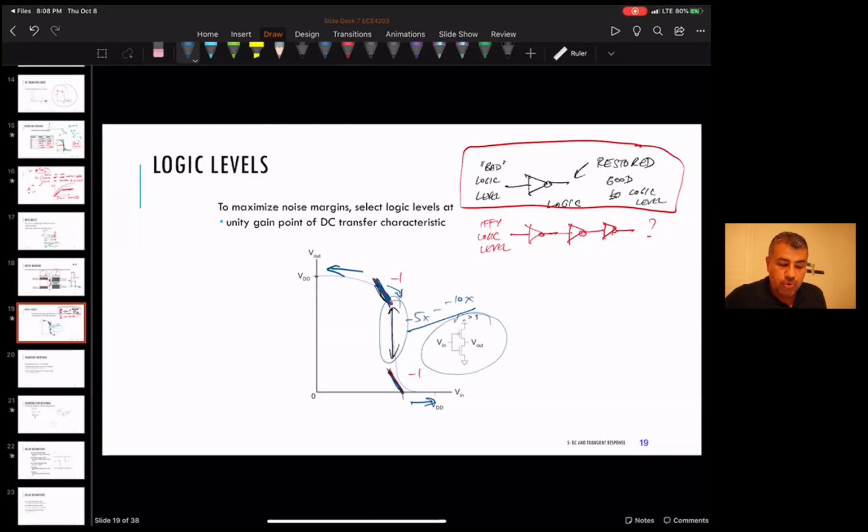Okay, so that's it for the transfer function, and you guys saw this by changing the relative widths. Theoretically speaking, the ratio you're changing is width over length, but length reduces the current of your NMOS or PMOS, while it increases the gate capacitance. So people don't do that in logic.